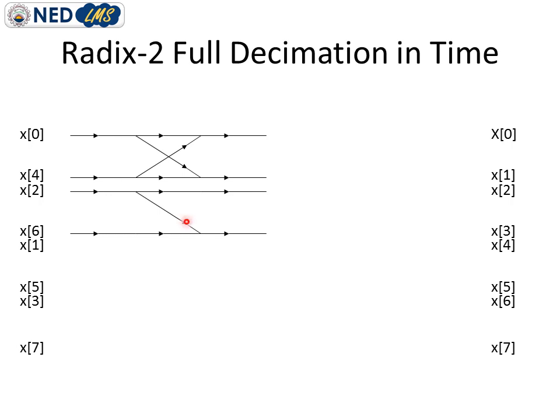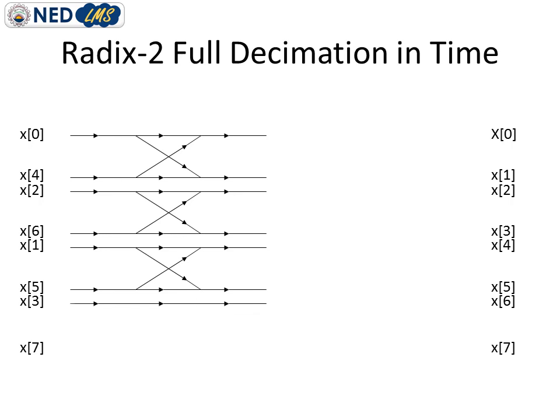First of all, straight lines, then 2 diagonal lines with proper arrowheads, because these arrowheads will guide us on the operation which we have to perform and in which direction we have to move with our results. And again these 2 lines straight and the 2 diagonal lines. So here the first stage is complete, where we are calculating 2-point DFT with each 2 samples.